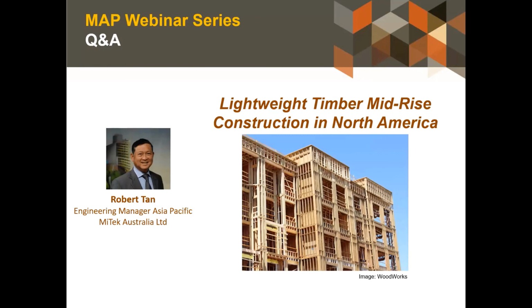I think for not only a timber building, any building at all, you've got to design durability into it to get the lifespan that you expect. And you look at some of the old timber structures in Japan and over in Europe, and they've been around for hundreds of years. So if they're designed correctly and maintained correctly, you'll certainly get the lifespan out of it. I'd have to agree with that. I think buildings fail not generally because of a big typhoon or earthquake, although that happens. Most buildings fail because of water ingress, leaks, other water damage. You're right. I think that's one of the fundamental things to ensure the longevity of a timber building.